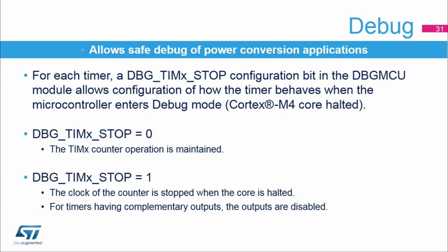This feature is extremely useful for applications where the timers are controlling power switches or electrical motors. It prevents the power stages from being damaged by excessive current or the motors from being left in an uncontrolled state when hitting a breakpoint.